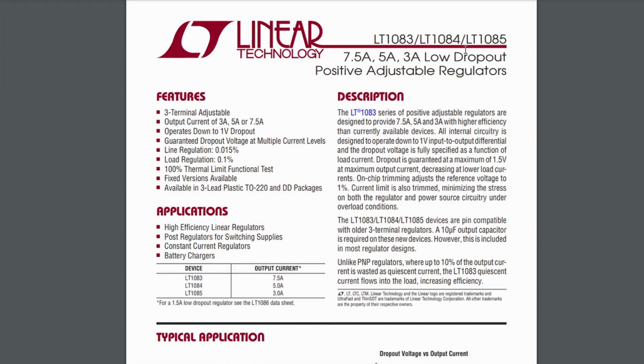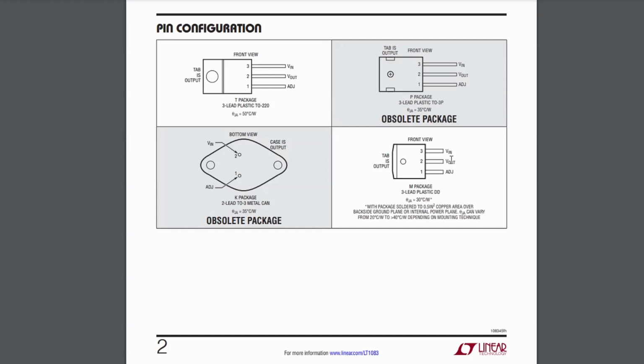One such model is the LT1085. Yeah, this is available in a very similar package and everything is the same. You can maybe also go for the adjustable version. So there with some resistors you can have a more accurate setting.